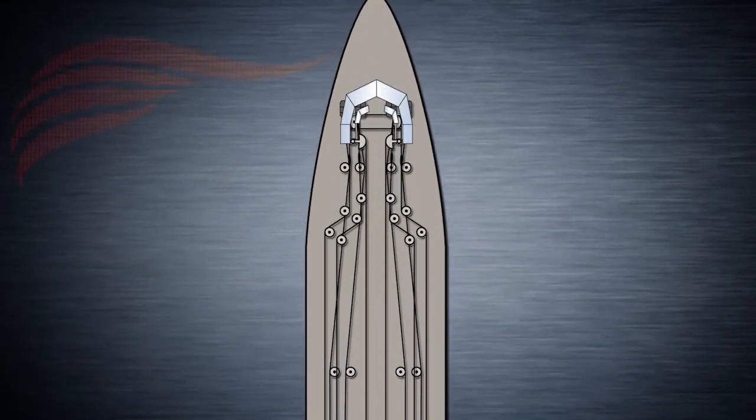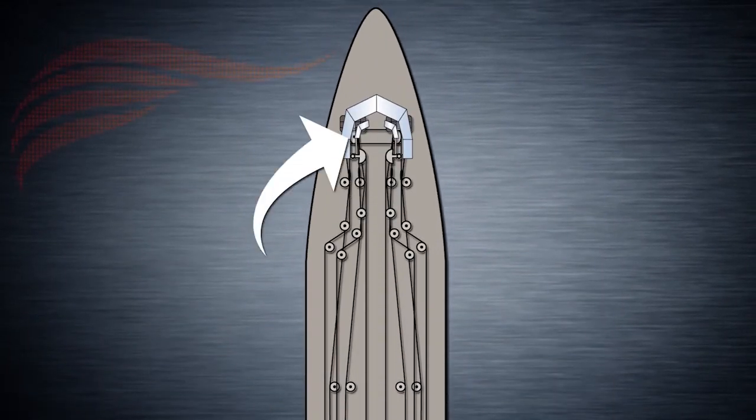In case one of the control columns becomes jammed, elevator control is still achievable from the other control column thanks to the elevator breakout mechanism. This provides added reliability and system redundancy. At least 31 pounds of additional force must be applied to use the working control column while the other is jammed. In this condition, when 100 pounds of force are applied on the control column, the elevator moves 4 degrees. In a total hydraulic failure emergency situation, this amount of deflection is sufficient for a safe landing flare.